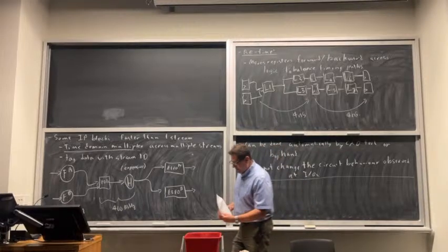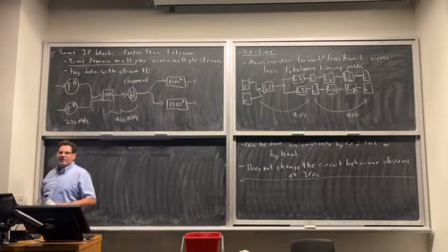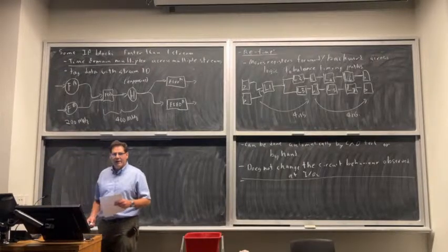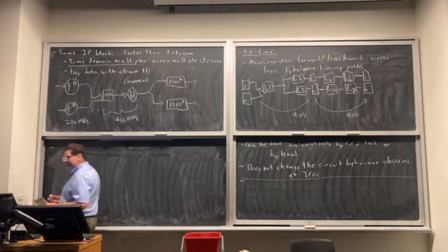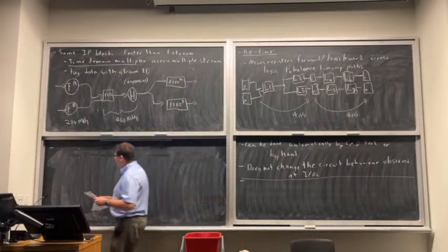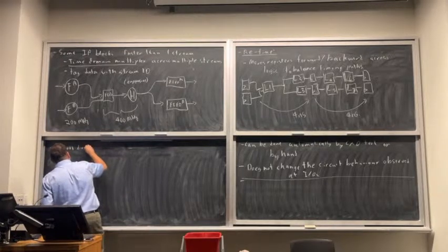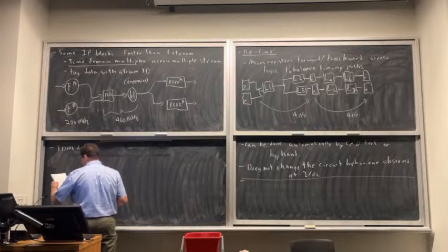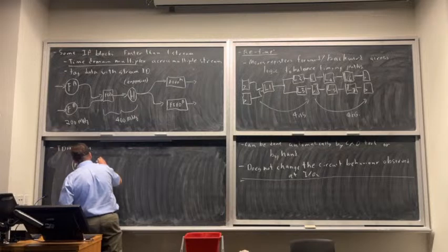All right, so let's see. Okay, so that TDM technique, time-domain multiplexing, that we just talked about, is a general technique that we can use in a bunch of places. So we talked about how you can't pipeline loops, which is a pain, right? They limit your clock frequency a lot of the time. But we can time-domain multiplex them. Okay, so let's take my little loop circuit from last week.